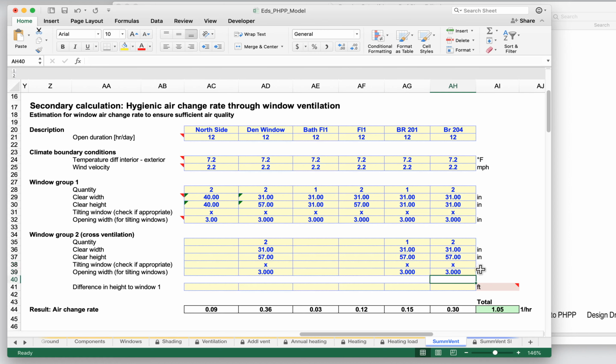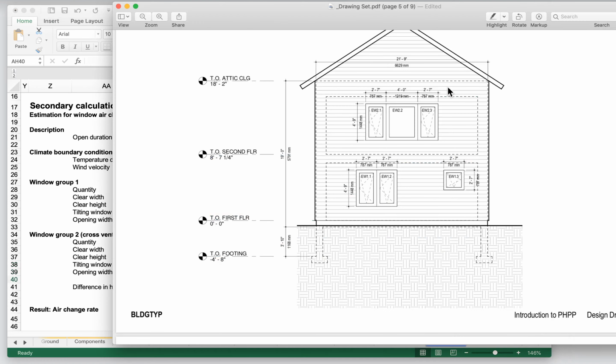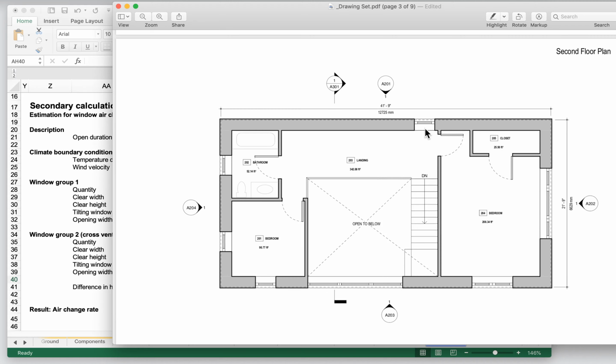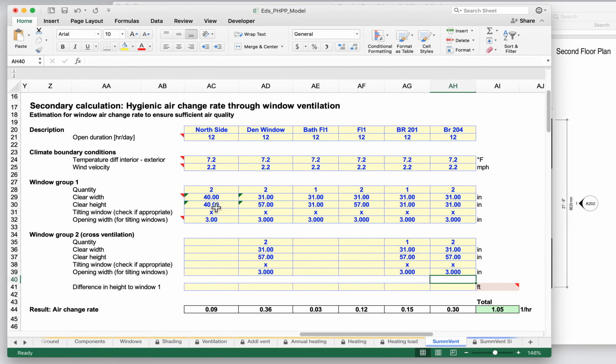And there we go. Now we could model out the last remaining windows there. We could add these little ones in, but this is how we would go through and model these for the daytime. Notice our total here, 1 ACH, significantly higher than the 0.2 that we were estimating and using as a basic value. So let's now set this as our daytime air exchange.